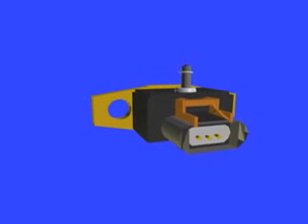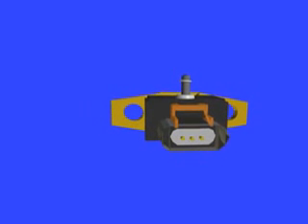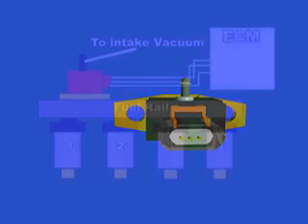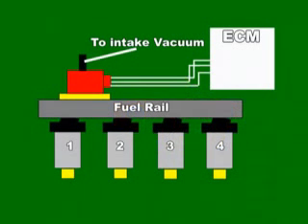The fuel rail pressure sensor is a 3-wire piezoelectric electronic pressure sensor. This means that the sensor's resistance varies as pressure changes. The fuel rail pressure sensor is also connected in line with an internal ECM voltage divider resistor network.